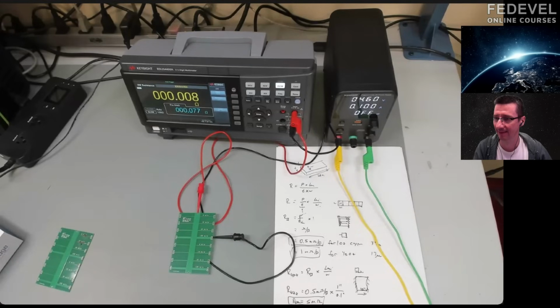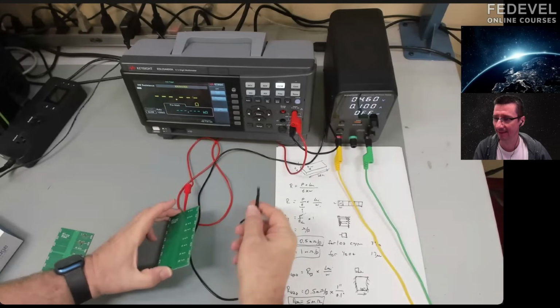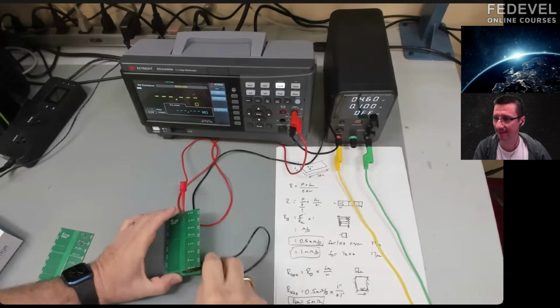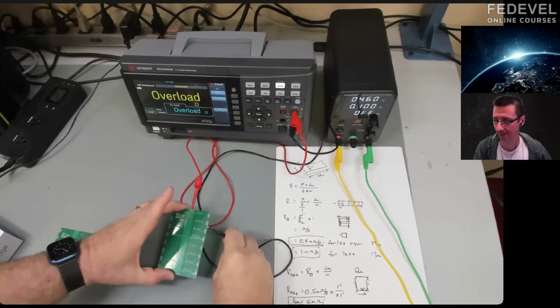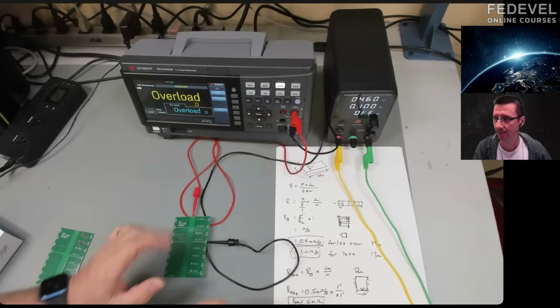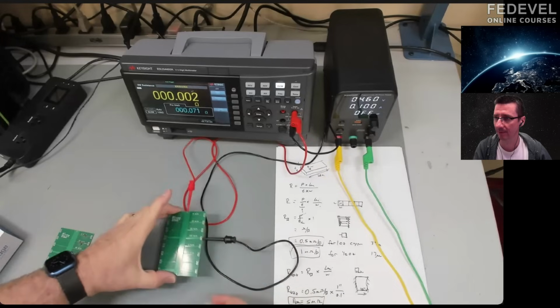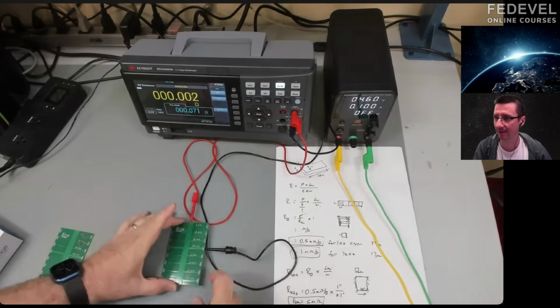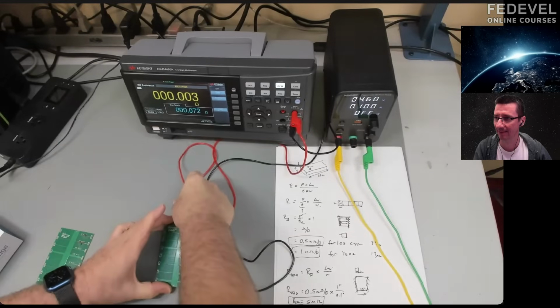Boy, it'd be nice if, and then I have the other problem of these wires, they had 70 milliohms of resistance. There's also contact resistance at the tips here when I connect them in, and that contact resistance can vary a bit as well. Look at that. I just did it again, and oh my gosh, now I don't even see that much.